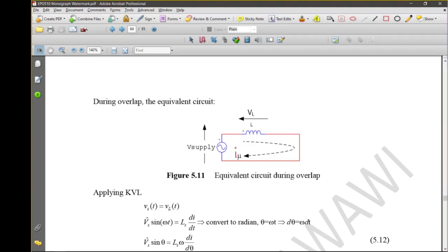You have to draw a current equation for IU, the overlap current, and this current must follow the flow of the current after the overlap. So it will follow the thyristor 1 current. You have thyristor 1 current flowing here, thyristor 2 flowing here, thyristor 3 flowing here. So it follows thyristor 1. You have to draw the overlap current IU to follow this thyristor 1 current. So draw that.